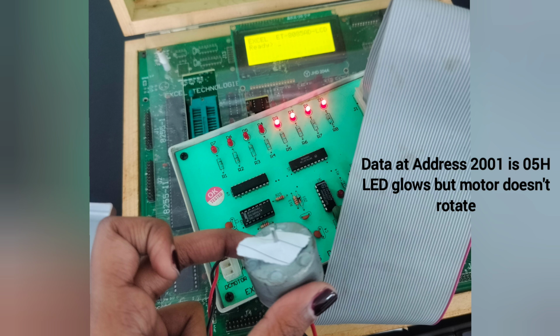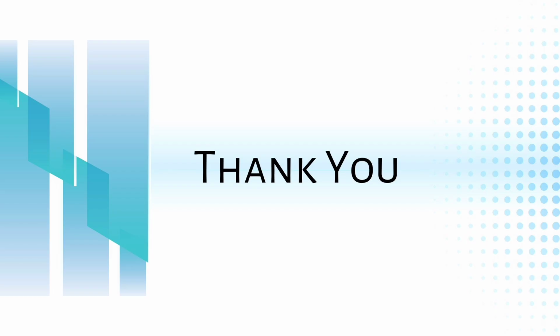This happens because the microprocessor cannot supply sufficient current which is required to rotate the DC motor. Thus, in this experiment, we successfully control the speed and change the direction using the hardware switch while observing LED indications. Thank you.